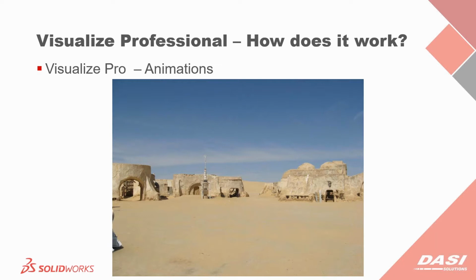This simple animation, which was about 8 seconds, took about an hour and 45 minutes to make this short clip. So keep that in mind when you want to render an animation, and it also obviously depends on your computer speed, if you render with the GPU and the CPU or the hybrid mode, and making sure that you have everything else basically closed out, right? So make sure you give yourself plenty of lead time to test this out, and you might even want to change something and then have to do it again later, right?